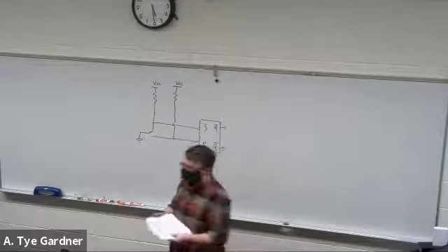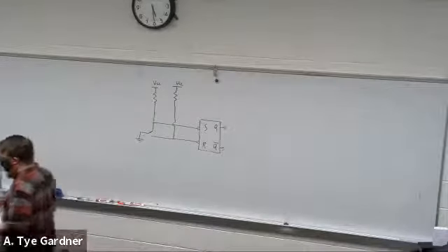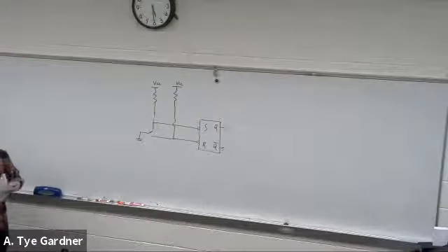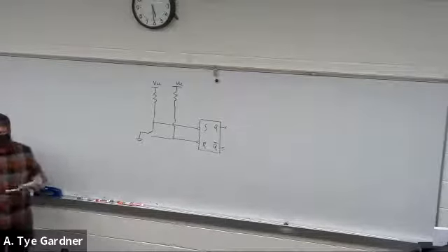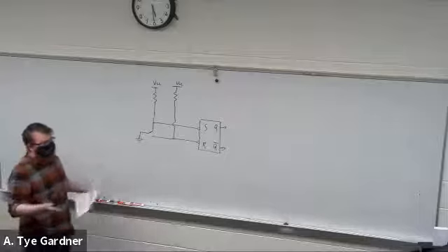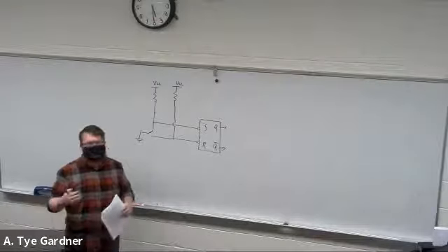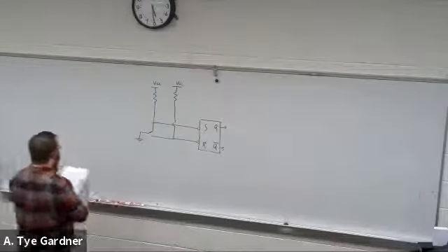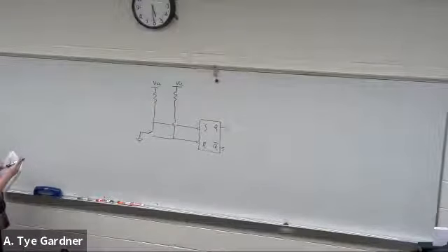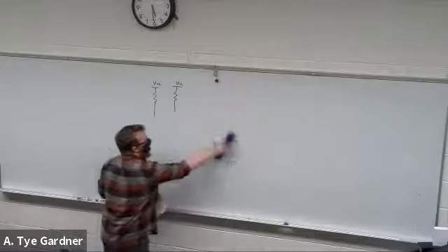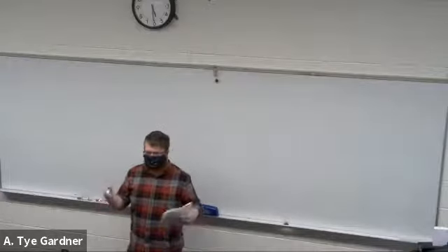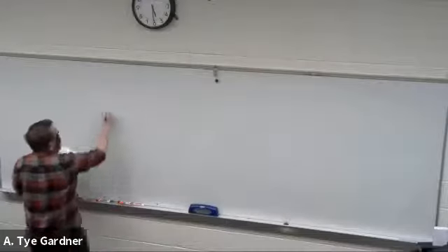But say we don't like set or reset latch. There's another kind. And there's actually multiple kinds, but the next one I'm talking about is a D latch, which really, depending who you talk to, my version is it's a data latch, which is to say that it latches onto whatever a data input is. So instead of just resetting or setting, it's going to latch onto the data. Now, the convenient thing for us is that the D latch really is just a slight modification of the SR latch. It was people like, well, we like this SR latch, but we need more functionality out of it.